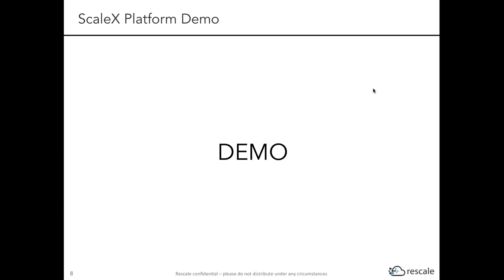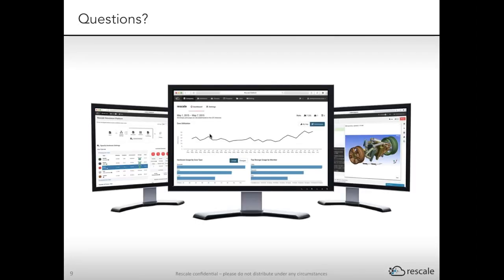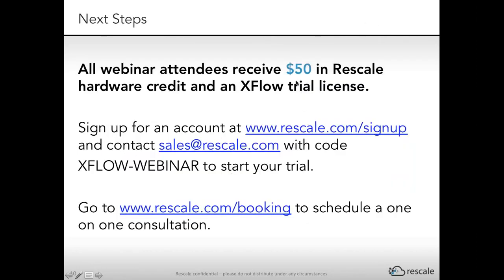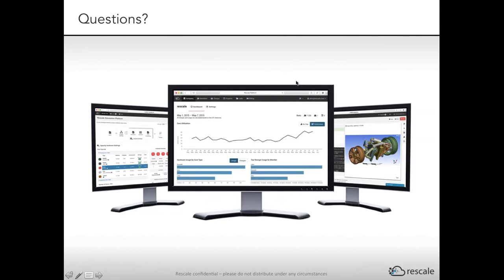Yeah, sure. So we've got the particle-based tracking multi-phase solver. As in the presentation, it's really good for high density ratios and strong inertial forces. The other one, the phase field, is another formulation of multi-phase solver and would be better to tackle small scales, low density and viscosity ratios, and anything that relates to strong surface tension effects. So they are very complementary and resolve different physics.